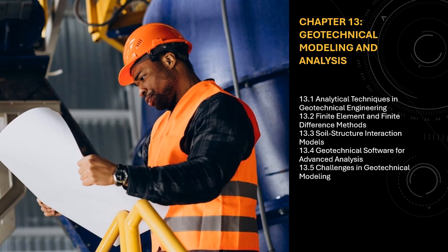3.3.2.2 Beam on elastic foundation, Boussinesq's model. This model is an extension of the Winkler model, where the soil beneath a structure is treated as a continuous elastic medium. In this approach, the structure, typically a beam or slab, is modeled as a beam, and the foundation's behavior is characterized by the distribution of stiffness along the beam. This approach is particularly useful for foundations with continuous load distribution.